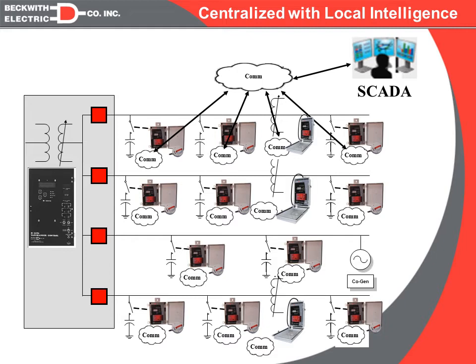With two-way communications, first of all, SCADA can now get back metering, which can help fine-tune this algorithm. If we have no intelligence out here, then all the metering was obtained at this level only. But now that we're adding two-way communications to each of these devices, and we can transmit back metering, we can get a better profile of what's actually going on across the entire system.